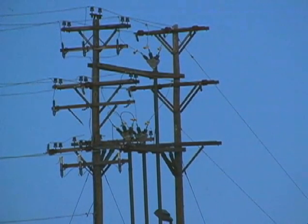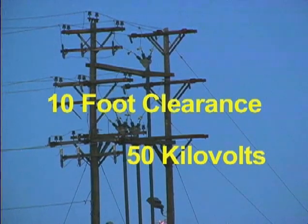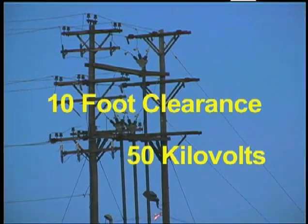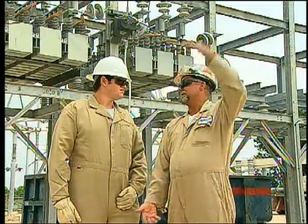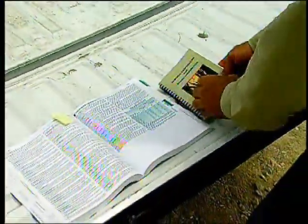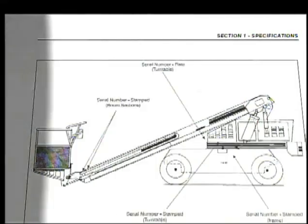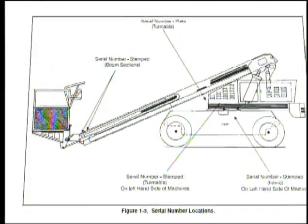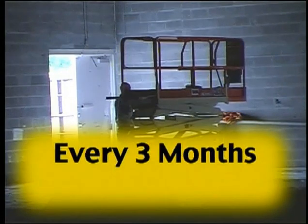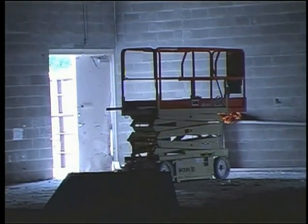OSHA requires personnel to maintain at least a 10-foot clearance of all power lines with less than 50 kilovolts. If a power line has more than 50 kilovolts, additional distance is required. Employees should consult with their supervisor to determine the proper distance needed. Electricians have different guidelines and should consult with their employers concerning this issue. Weather conditions must be considered before using any lift. Additional inspections may be required by the manufacturer. These usually are to be performed every 3 months or 150 hours of operation, whichever comes first. These inspections should only be done by a licensed professional.